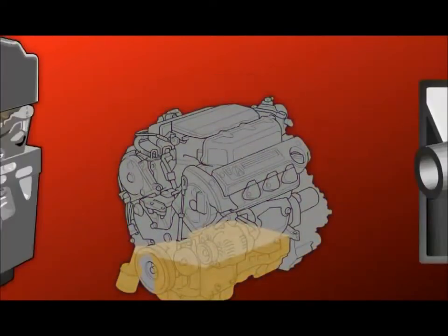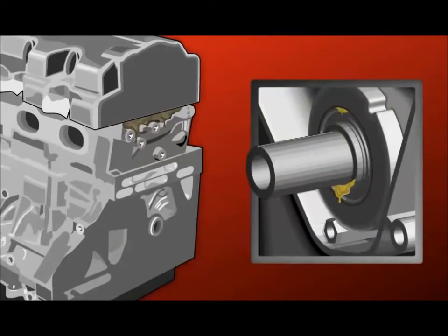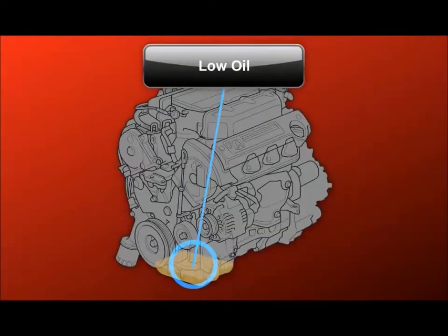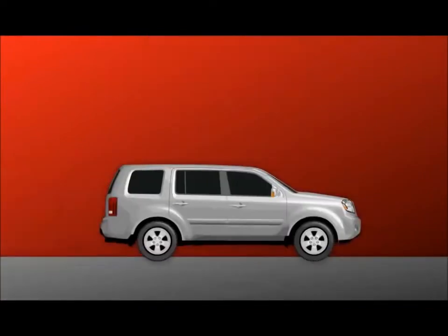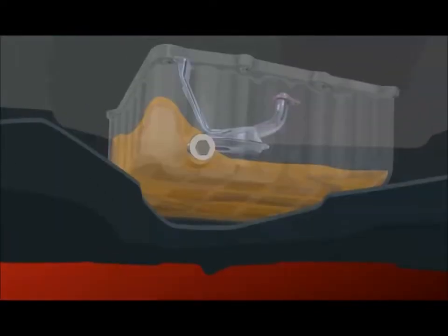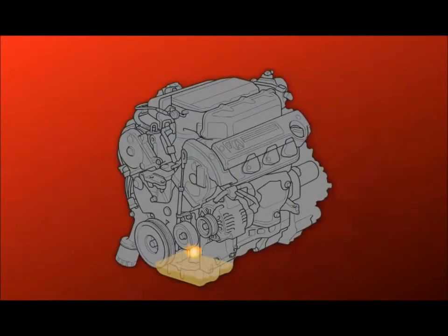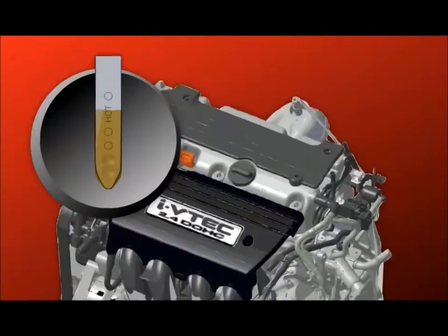Excessive oil can also cause idle vibration, power loss, or even limit engine RPM. Finally, excessive engine oil may increase crankcase pressure, forcing oil out of the engine through seals or gaskets. Low oil level causes different symptoms. Hard braking or cornering can expose the oil pickup, drawing air into the oil pump and dropping system pressure. A low oil fill also reduces the system's ability to dissipate heat, increasing overall crankcase temperatures. For all of these reasons, always check the engine oil level before further troubleshooting.